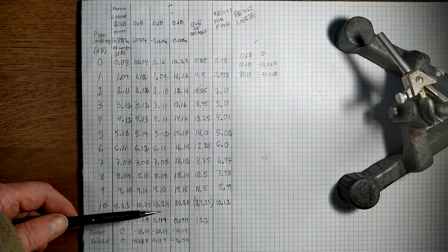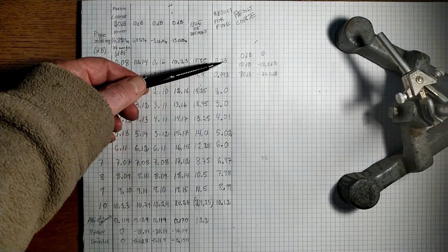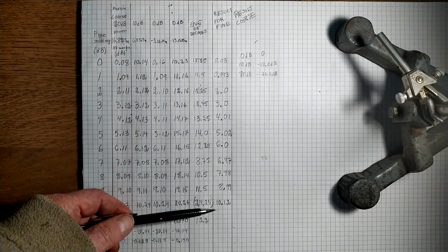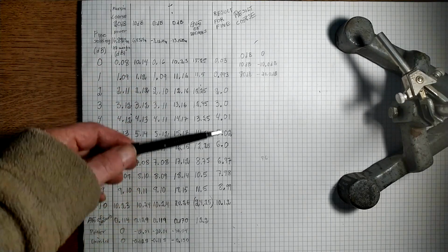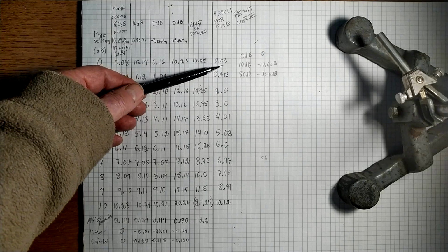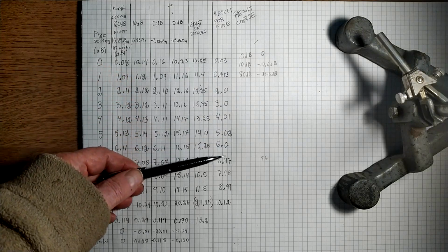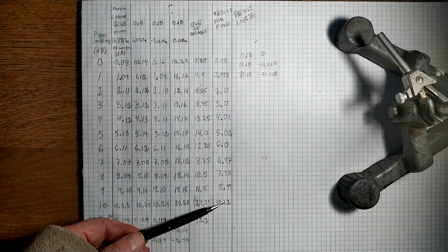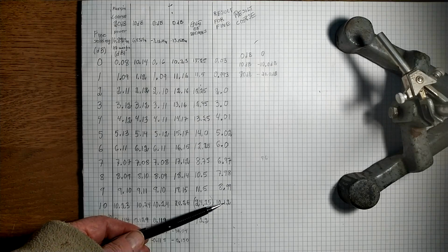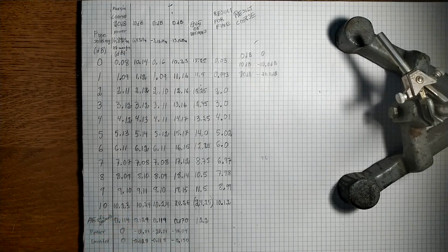And the result of all of this is that here is the attenuation for the different settings of the fine knob. They all are within a fraction of a tenth of a dB, except for the 10 dB, which differs by 0.12 decibels from the average of the other ones. And that is an error of 0.1 dB, nothing that they will worry about.